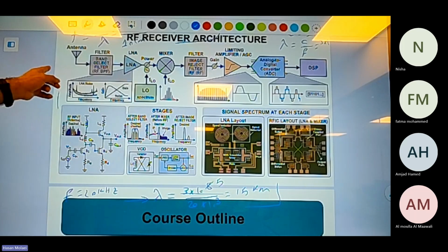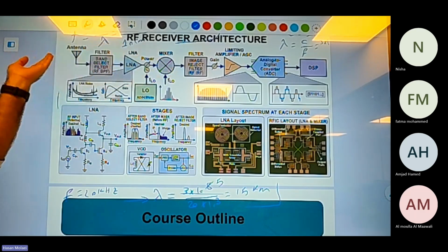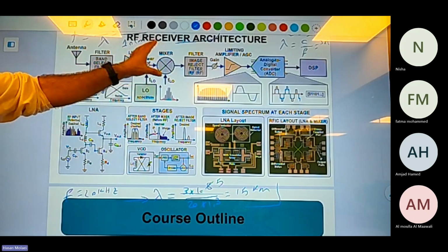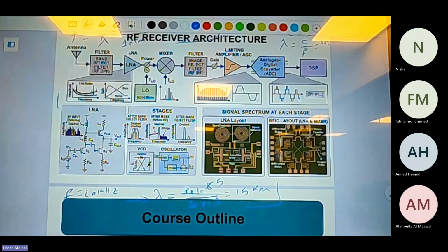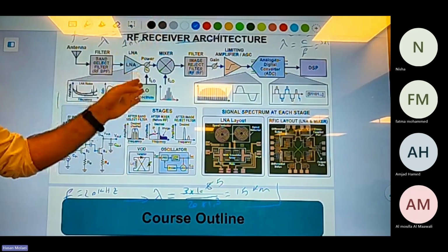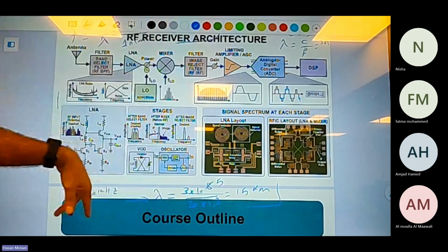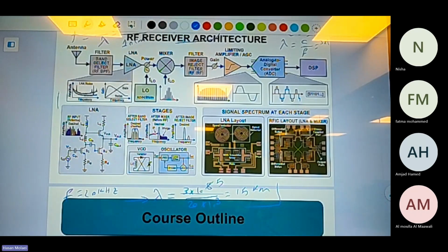Yes, that's why we have to increase the frequency of the signal to one which our antenna could receive. After that, we send the signal. Here it's a receiver. We have a signal in a frequency of 100 gigahertz, and we should bring it down. We use this element, which you will learn later as a mixer. And we have another filter, which is an image reject filter, that right now you don't have any idea about, but you will learn. My point is, we have these blocks as filters.